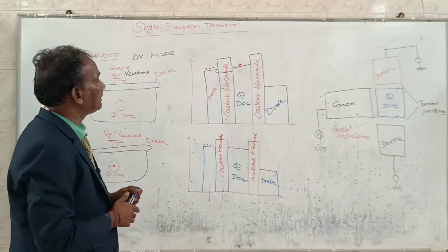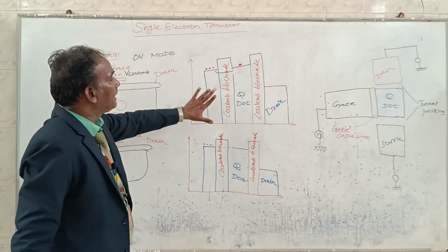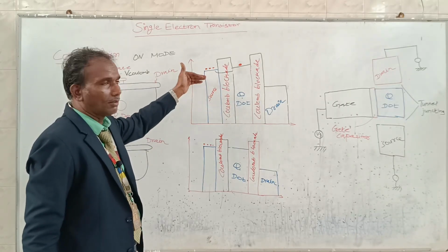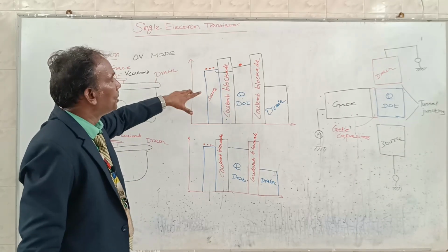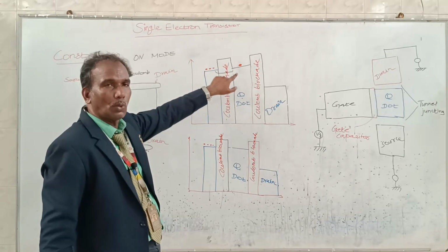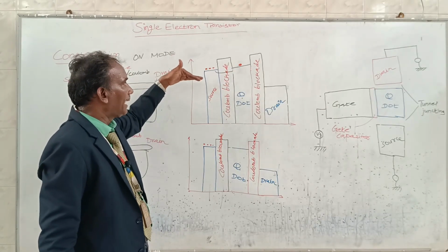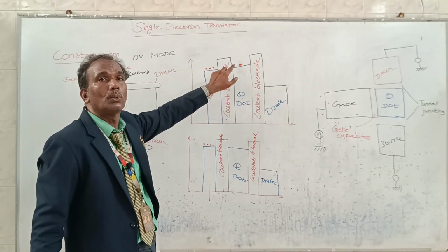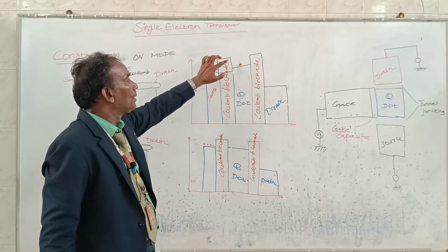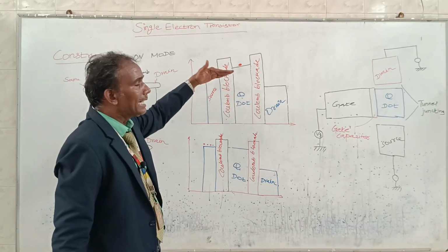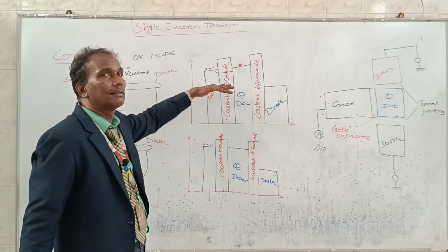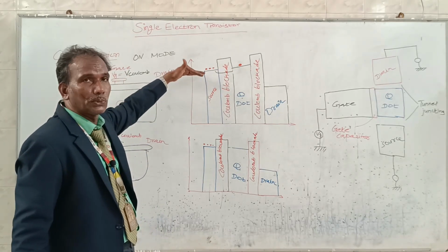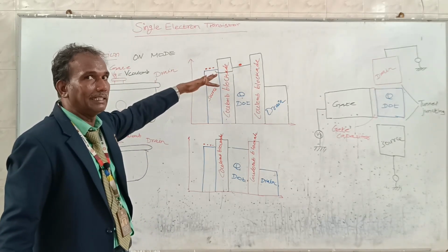So as we discussed earlier, when the situation is favorable to the electron, it is able to move from source to quantum dot by tunneling through the Coulomb blockade, and it will reach the quantum dot, so that the energy level of the quantum dot rises up to the energy level of the source, as we discussed earlier.